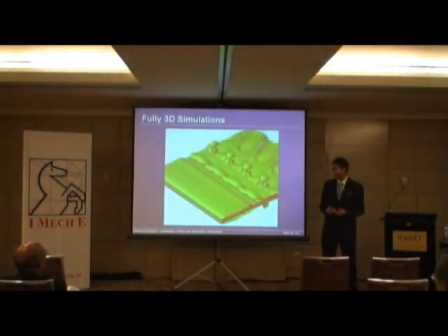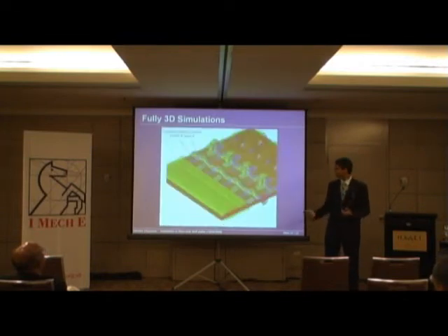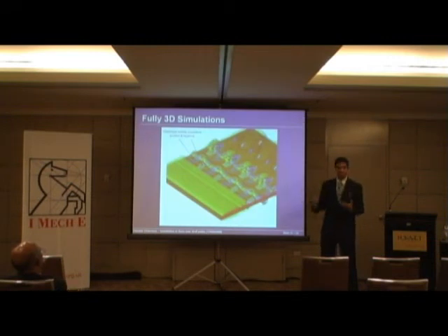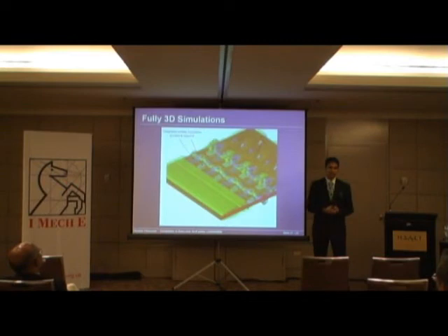We can overlay that streamwise vorticity, that twisting measurement, in light blue and dark blue, and you see the same pattern emerging. So given that this is a sort of an independent check of the results, this confirms our finding that the elliptical instability flow pattern is definitely the key player causing turbulence from the beginning.